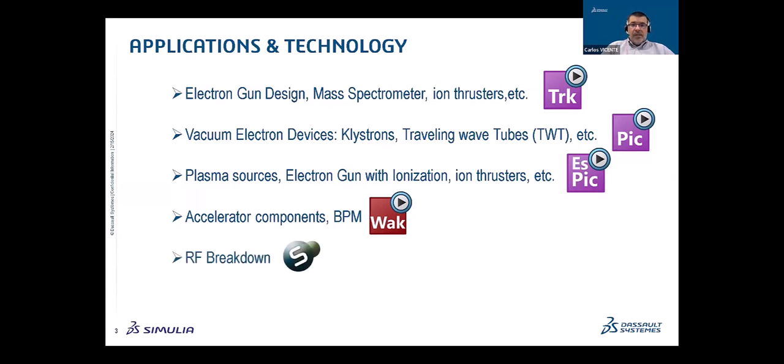And finally, regarding which is a solver, but also a kind of independent tool in the CST Studio Suite environment, we have SPARK3D, which is a dedicated tool for RF breakdown analysis, especially for space applications. In this case, we can analyze RF breakdown, both multipacting and ionization breakdowns. In the case of multipacting, we are using an ad hoc particle tracking solver. In the case of ionization breakdown, we are solving the electron density continuity equation by means of an eigenmode solver.